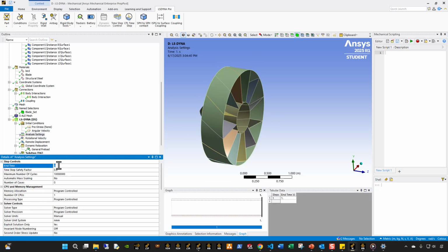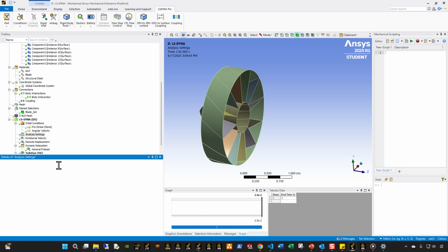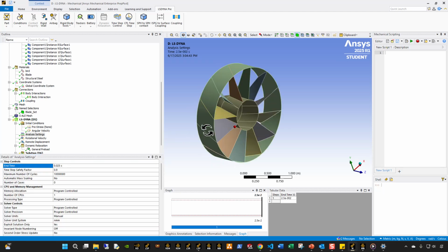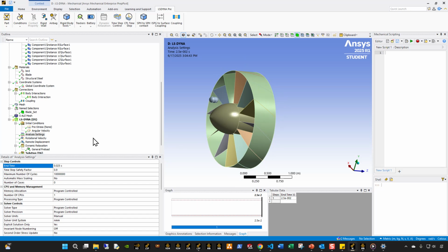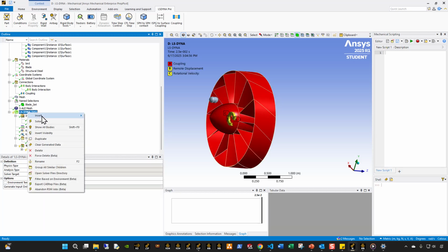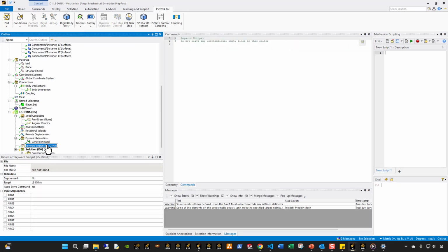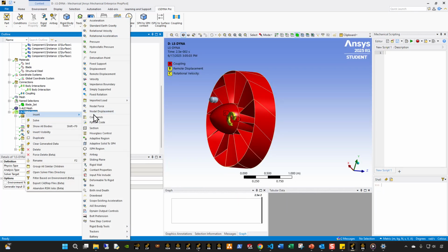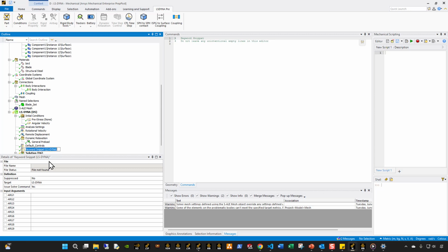The termination time for something like this, we're gonna put at 0.025 second, relatively short duration, right? And this basically defines how the blade itself is going to be moved, right? And we're gonna add a few control cards. Let's add a default control card. Now I'm not going into detail of exactly what I did with the default cards. I've done a lot of these in the past, so if you're interested, you can check out the other videos, right?